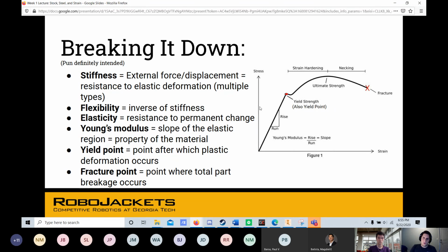The other thing that you would want to keep into consideration, and this is typically what's used as a criteria for failure, is called the yield strength. I mentioned that a brief bit before. Essentially, the yield strength refers to the stress at which the material will start to permanently deform, right? So when you design a part and you do your calculations, and you'll probably have to ask your upperclassmen to help you out with a lot of that because it honestly gets pretty involved and a little complicated, as long as your stresses aren't going above that yield limit, you'll be completely fine.